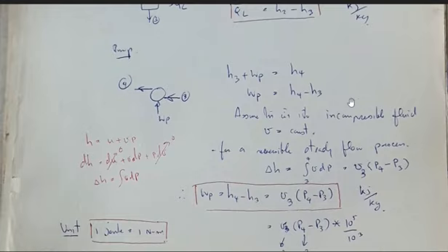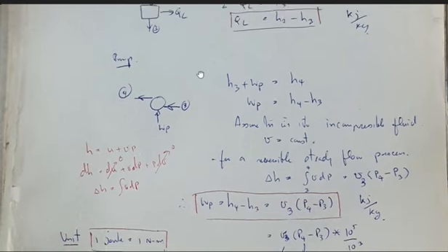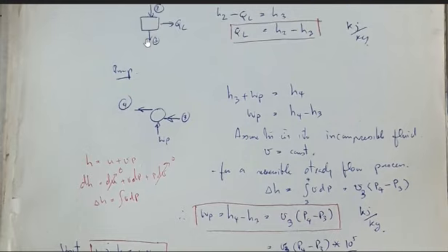And for the pump, after the water leaves the condenser, the water will go through the pump at state 3, and then we will provide work to the pump to pump the water up to the certain pressure that we want, which is the boiler pressure.